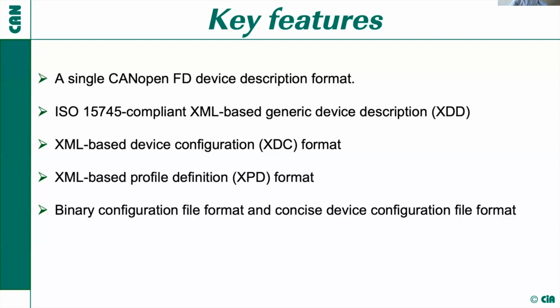Another topic, which we also have in development, is configuration files in binary format and the concise device configuration file, known as concise DCF, also from the times of classic CANopen. Those things we want to keep, and we also want to reuse or redesign a binary configuration file format. It was not designed into classic CANopen. It was partially manufacturer specific. Now we want to make it a standardized format to be used. Because of certain cybersecurity concepts and considerations, such a configuration file will be less prone to cybersecurity effects or attacks from outside.